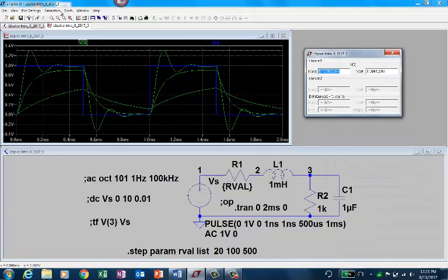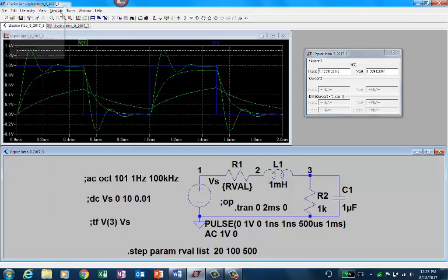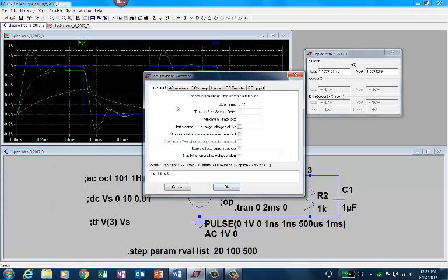If I mention the simulation, there are a lot of options you can use. We looked at the transient response, AC response, DC sweep, and noise analysis. We didn't do that one. DC transfer works like Thevenin's equivalent. You put a voltage source, see where your output is, and it gives the equivalent input resistance, output resistance, and the gain of the circuit. Then there is the DC operating point, the DC analysis. For a basic circuit, mostly you do the DC operating point.